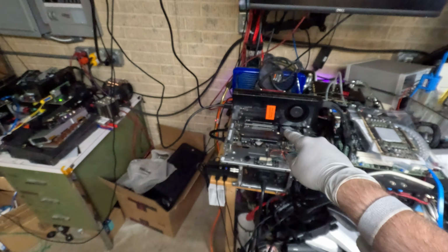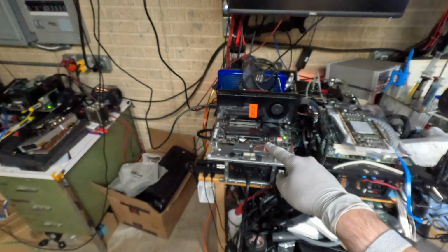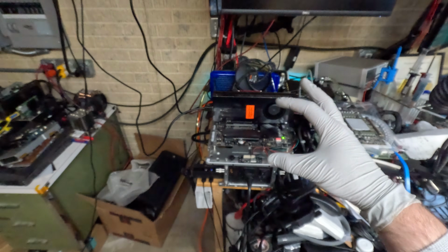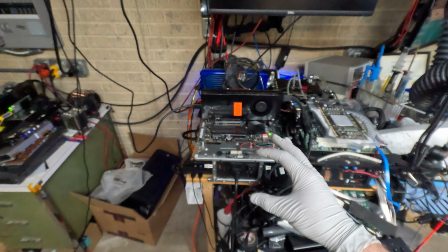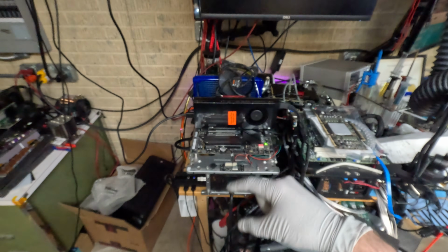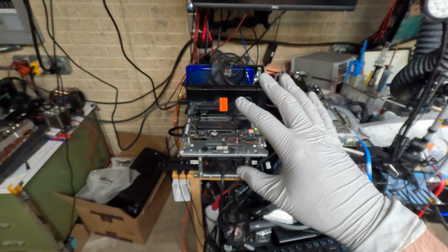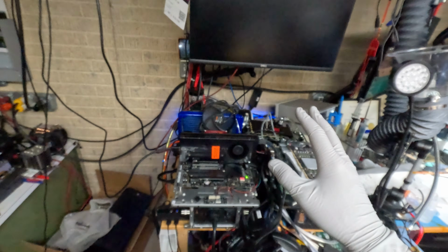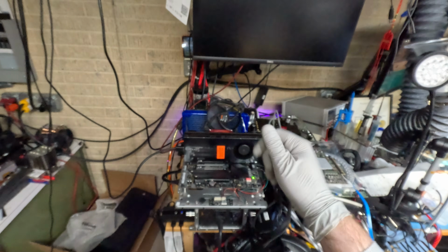So now I'm going to put the card on the workbench, which there's currently a card right here running right now. But I'm going to take that card off and put this card on, and we're going to test if this card crashes like it used to under the comfyUI workload. Basically, this is only the old core that was having issues on comfyUI. And so if the issue is related to the core, any kind of memory controller issue or any issue with the chip select function, then it will show up on this card with the brand new PCB and brand new memory.